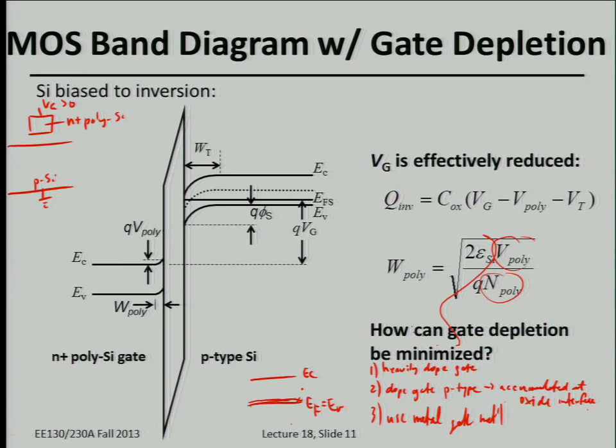If you use p-type polysilicon as the gate material rather than n-type polysilicon, what is that going to do qualitatively to your NMOS threshold voltage? The work function of p-type silicon compared to n-type silicon is much bigger. So what does that mean for your threshold voltage? It's going to be 1 volt higher. Generally, nobody wants a transistor with over 1 volt threshold voltage. So practically, the threshold voltage is too high if you do this.